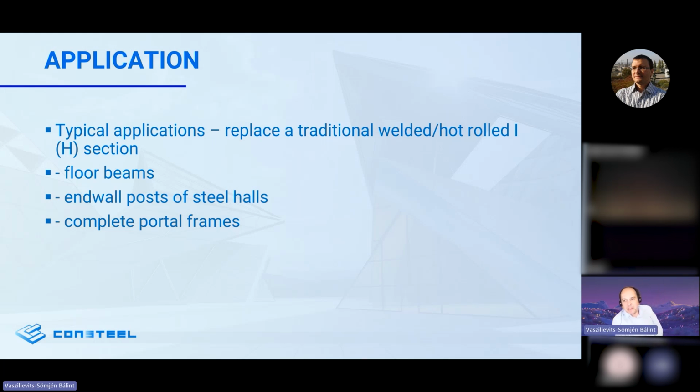Double C sections are very commonly used when someone works with cold form sections, because this is the closest similar section to the most traditional I sections used for steel structures, without any weld or other requirements. The two C sections can be positioned back to back, immediately close to each other, or with a gap, fixed at certain positions with adequate joining devices such as bolts, screws, rivets, or welds, or anything basically.